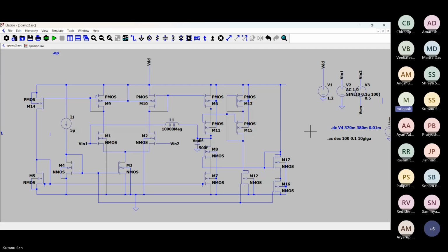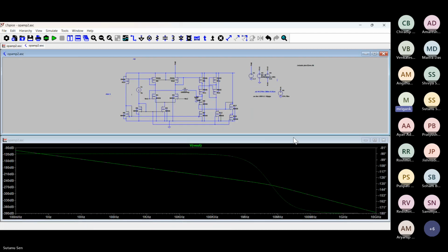But for the open circuit case, when you have to do the open loop analysis, in advanced tools like Cadence, there are ways in which it can be done. There is the open loop analysis setup where you don't have to necessarily open the loop and fix the DC point, just like what we are doing here. But here this feature is not available. So this is an alternate trick just to avoid that DC sweep.